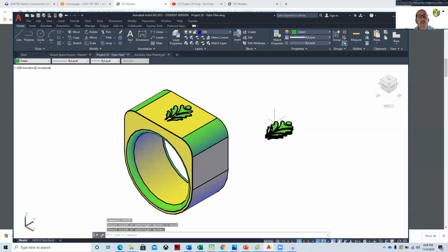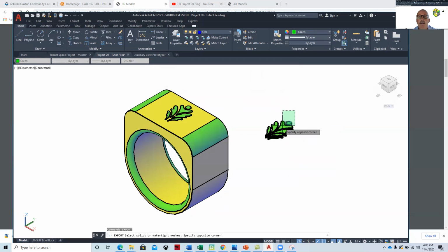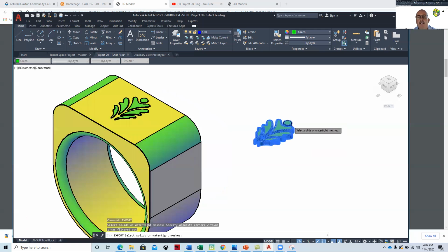And I'm going to export this one over here because I'm not quite ready to go into dual extrusion, but I can show you how to extrude them and print it with a single head nozzle with 2 different colors, which is actually a lot more practical. So we're going to export this one. And I'm going to export this one as logo. And then I'm going to set and export all of these parts right here.